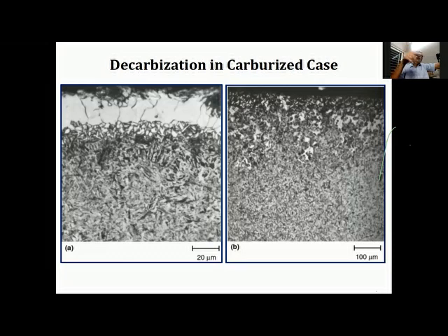So the moment you get an indication, this may not happen suddenly. So you have to keep on studying the microstructure batch after batch, and the moment you see some amount of decarb, immediately we have to take action to find out why it is happening and correct the situation. Many times you'll have to replace the fan unit totally, or you may have to shut down the furnace and then do the needful. But those are the two conditions under which it can happen. Next, please.